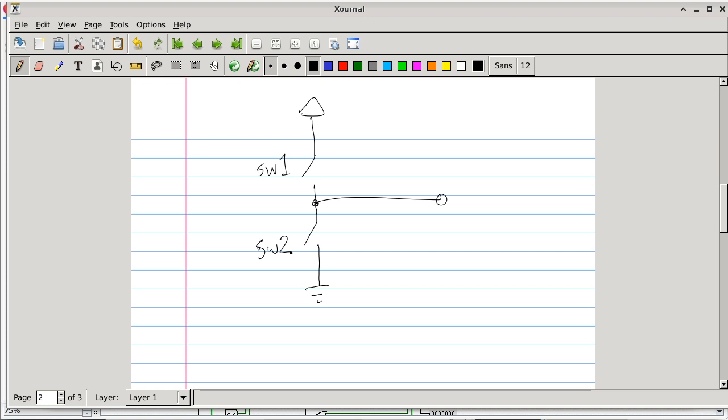The fluorescent lights emit a lot of electromagnetic interference signals. Your cell phones do, your Fitbit also does that. All the computers that we have emit electromagnetic waves. So all of those electromagnetic waves would induce current onto this wire. And as a result, this point here, your test point, is going to experience very slight changes of voltage, but it will be constantly flipping around. That's called the floating state of a circuit.